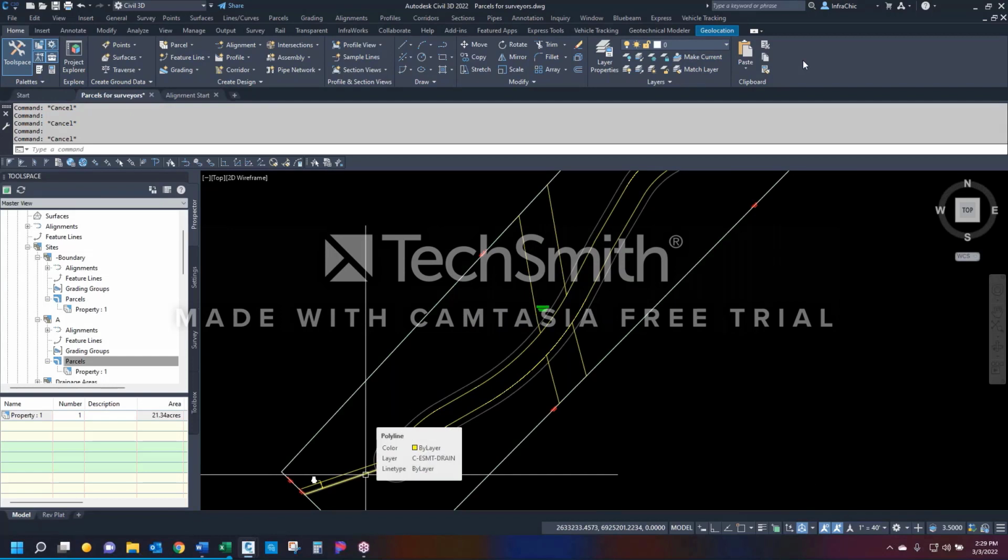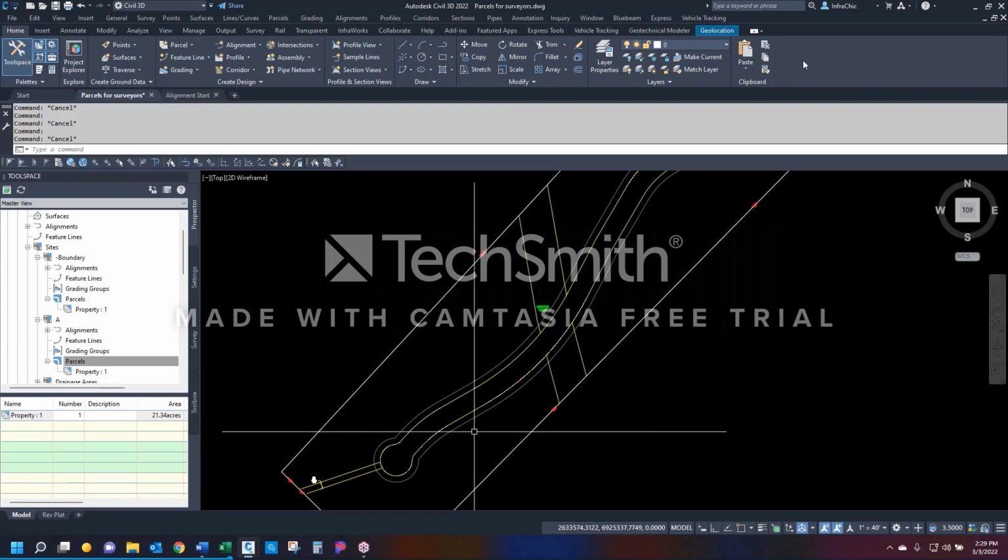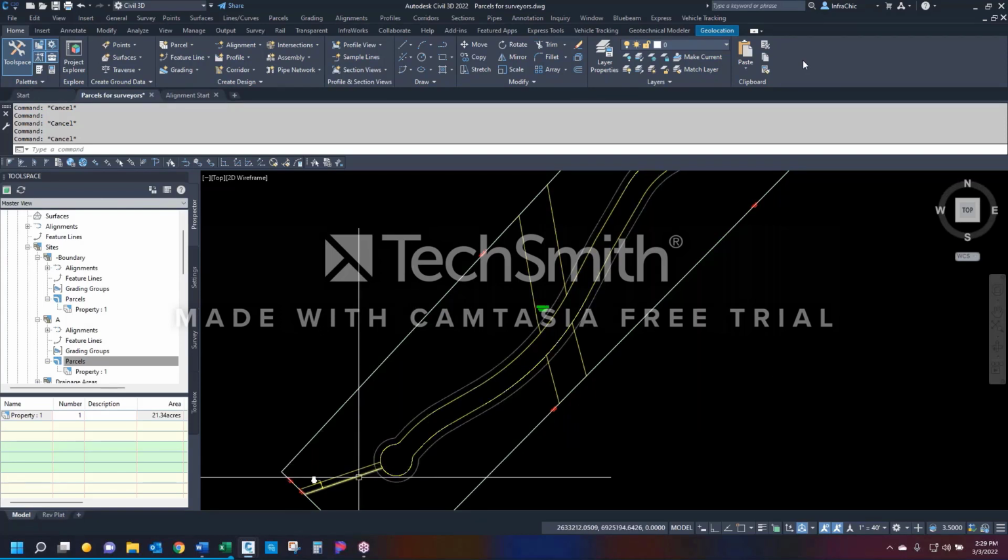Okay. Now, there's some other things. In this jurisdiction, this is Kaufman County, Texas. Kaufman County states the following. Drainage easements will not be included in the overall lot area of your new lots on your preliminary plat. So this is a drainage easement down here. It's 20 foot wide. That means this cannot be included in any new lots. The lots must stand on their own without this drainage easement, and they have to be, in this case, 1 acre in size or greater, because that's Kaufman County rules.